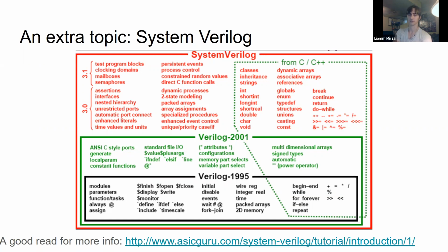Essentially, they create an abstract model of the circuit with SystemVerilog using the object-oriented components, because it's a lot easier than with just regular Verilog code. Then they compare the outputs and inputs driven through both the Verilog version and the SystemVerilog version, while the SystemVerilog component also generates the inputs that are tested.